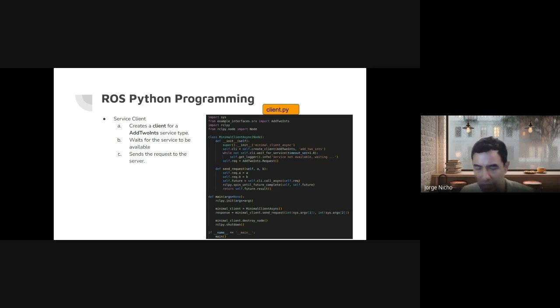They provide a ROS service which you can call, where you build your request, and the request basically defines where you want the end effector to go in your coordinates. Whatever coordinate system you're using, you would say, I need to move the end effector to X, Y, and Z position in this orientation. And that server will compute the movement required to get the end effector to that particular point.